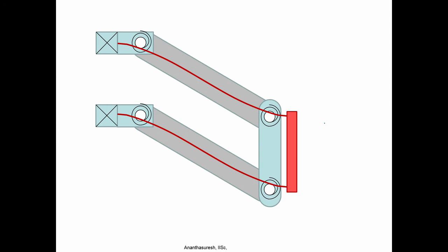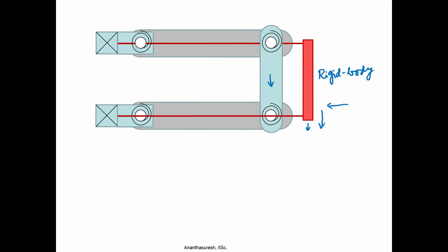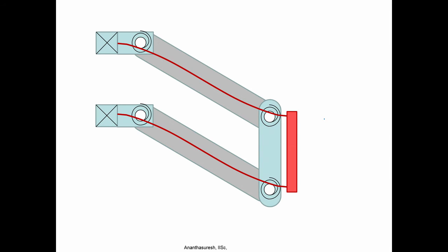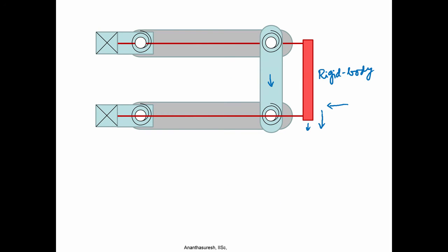Okay. That is how it is going to deform, and that is how our parallelogram linkage also is going to move, right. So, our parallelogram here moves in this diagram. It looks like the rigid body is stretched a little bit, but that is just a mistake in drawing, but it is a parallelogram linkage that rotates and moves closer to the fixed end, and that we can model with again one parameter, because if you see this parallelogram mechanism, there is only the rotation of this, that is same as rotation here, right, that if we call this theta, and that is one parameter for this mechanism, which consists of two elastic beams undergoing large displacement.